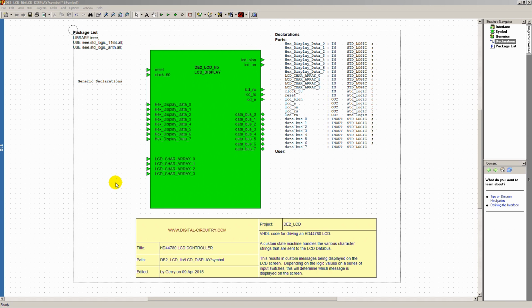Eventually I might get into showing you how to create your own custom fonts that you can program into the LCD display, essentially creating your own fonts or graphics. But that will be a later video. For this series, I'm going to start out by explaining the concepts of how the HD44780 LCD display operates and the signals that are required to initialize it and then to send specific data on the Databus to display specific characters.